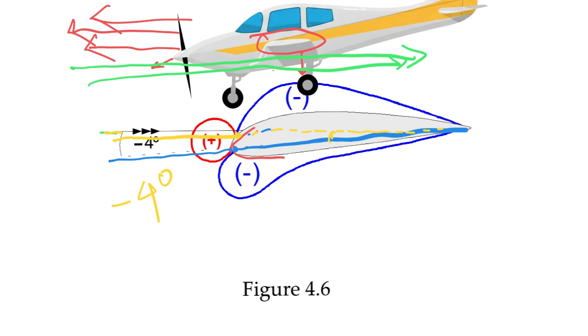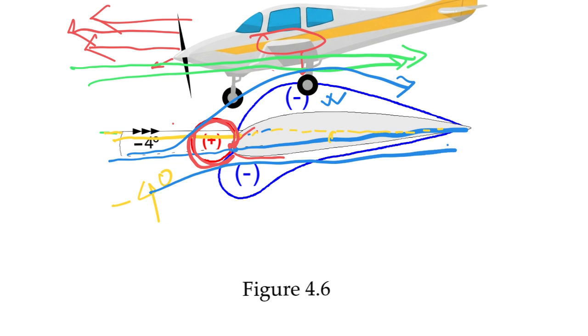Now already you know about this stagnation point and this dynamic pressure half rho v square here. That is why some positive pressure is happening over the leading edge. The air that is going above the wing, the static pressure is reduced here above the wing. Also some air is going below the wing and here also the static pressure is reduced.